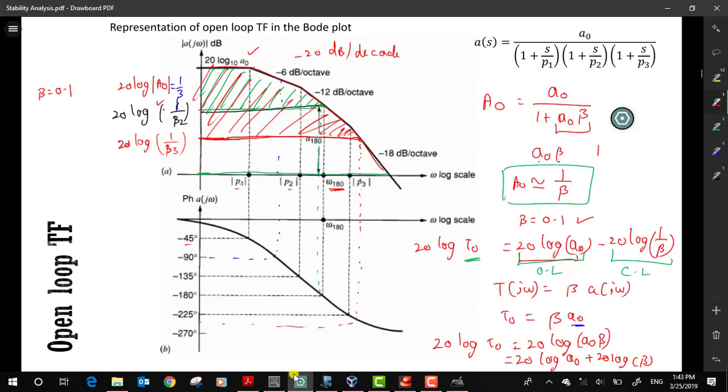So now that you are being asked to design an op amp, and we know that this op amp has 3 or 4 poles, and you have given this for a commercial purpose, a guy like me can have a beta factor that is equal to 0.1, or even a feedback factor which is equal to 1, which is nothing but a voltage follower.